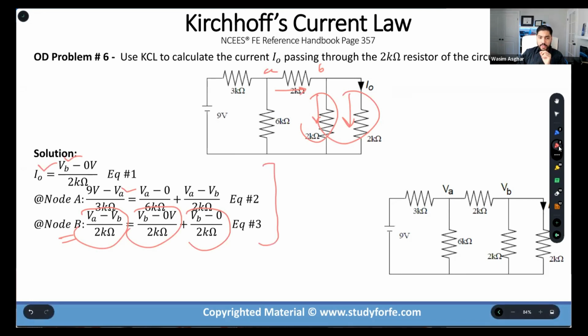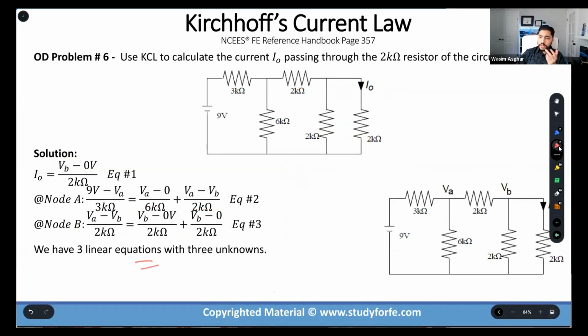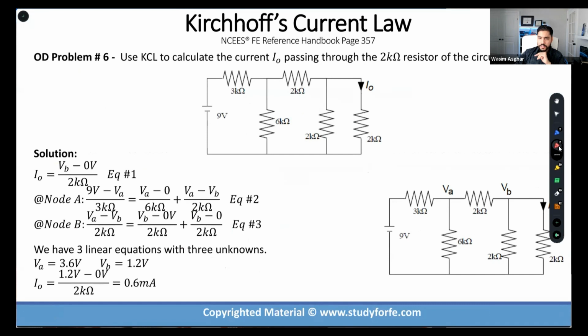Your actual test is coming up with these equations correctly and consistently with your circuit assumption. The rest is math, okay? Don't get fixated on the math. This is the key point. Does it make sense, guys? Is it clear? So we have 3 equations, 3 unknowns, and then we can solve them using the calculator, back substitution, whatever. The math is not the focus over here. The focus is how we crack these problems. So in KCL, be mindful of your circuit assumptions. Make your equations talk to your circuit and vice versa. Don't arbitrarily flip the direction of current while writing at node A versus node B. Very common mistake. All right, guys? Make sense? Let's move on.